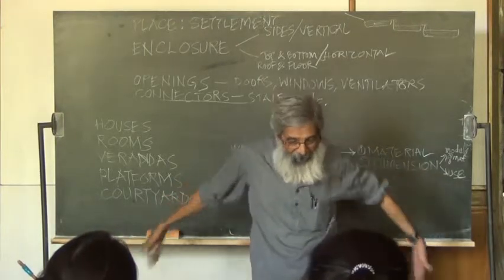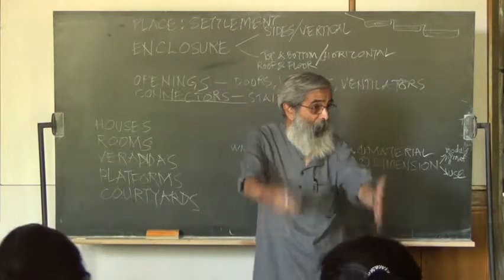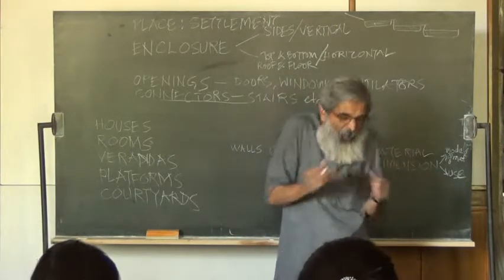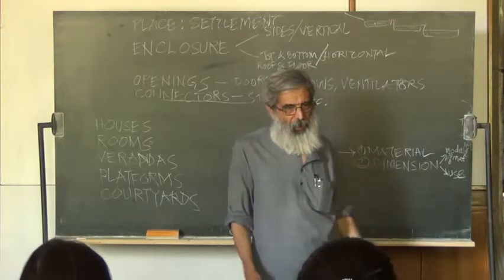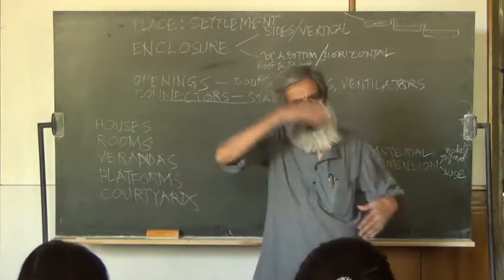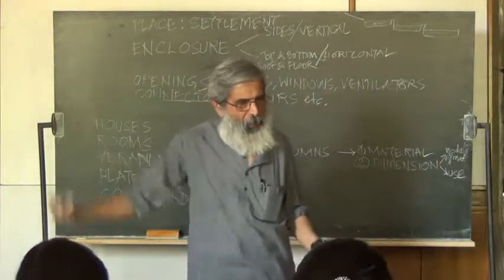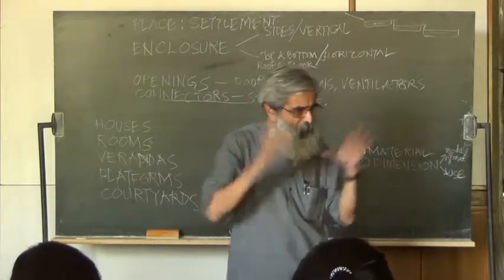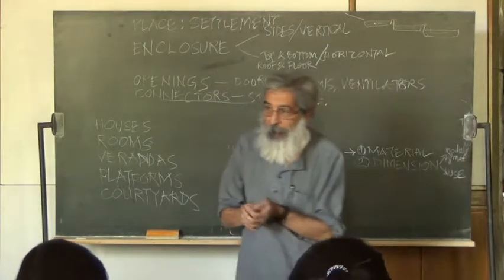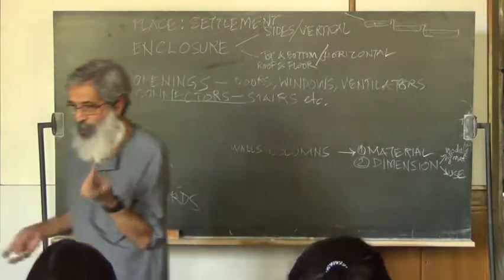The minimum clear dimension of a room I need for that with a very tight space in between is 2400. And I can go to the next dimension. If I have a WC, I will need certain kind of clearances, etc.